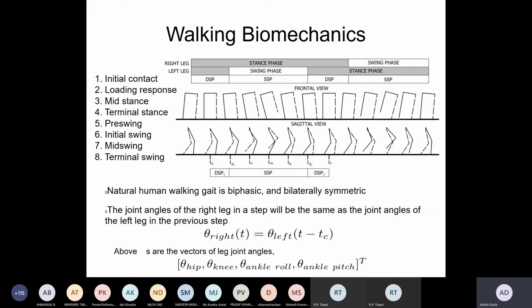Now in the two patterns, first we are in a two-legged stance. You're standing on two legs, as shown in the figure here. Then we move the body to one direction. Why do we move it to one direction? To ensure that the projection of the center of gravity falls inside the foot on the ground. So in this position, the projection of the CG is there. Your CG is on your foot on the ground, so you're balanced.